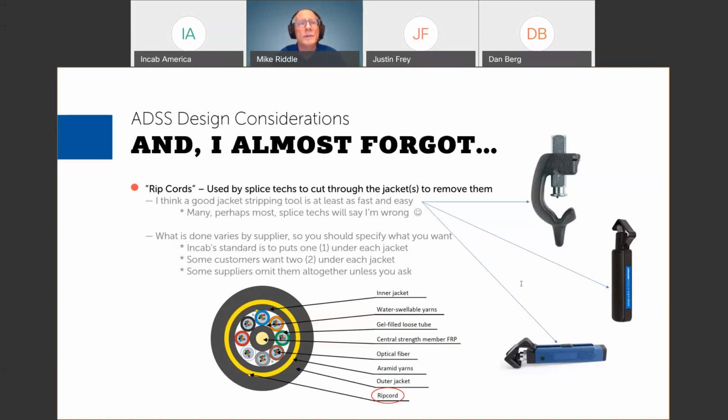And for that reason, the more common solution is to put just a plain black jacket cable, a duct type cable without armoring, in a conduit in proximity to an underground circuit. The other solution that you could do is what I showed you before, a fiberglass reinforced plastic rod armored cable that could be direct buried.